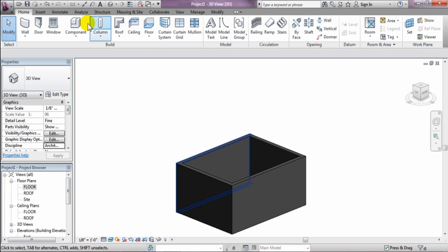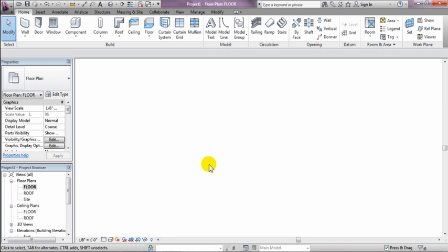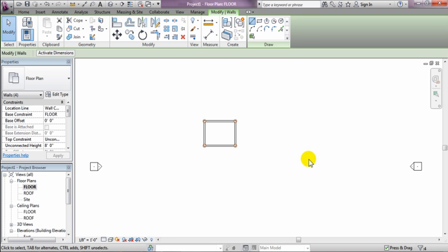And I chose to do it in my 3D view because I wanted to show you the changes happening. But I could be in my floor view and do the same thing. I can just highlight all my walls like this and change all their heights as well. Going to the bird's eye view or the floor view is a good way to change things because the computer isn't going to have to show you what it looks like in 3D, so things will go a lot faster if you do them in the floor plan view and just use the 3D view to see what it looks like when you're done. So I would recommend working in this view all the time.